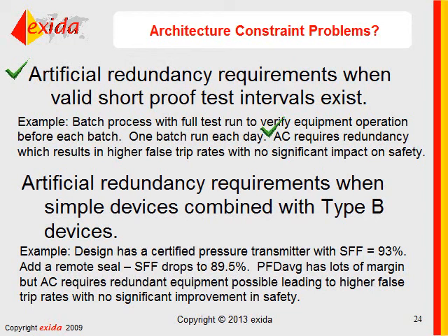That means higher false trip rates with no impact on safety. And that's not a good design. I've seen artificial redundancy requirements when simple devices are combined with type B devices. If I combine a type A and a type B, which you really do if you have